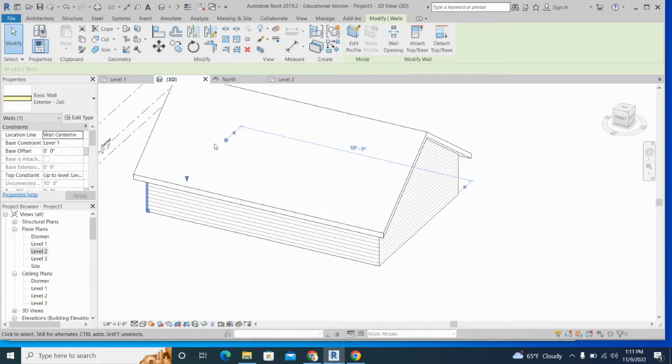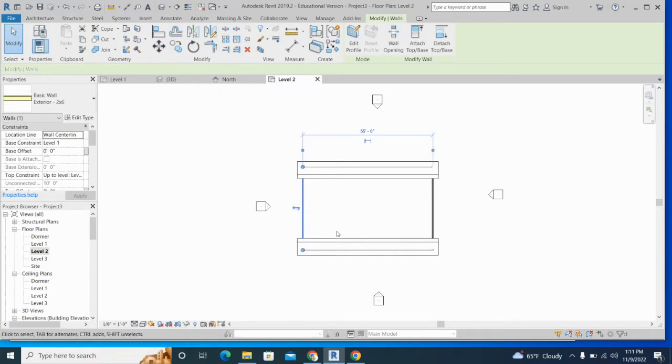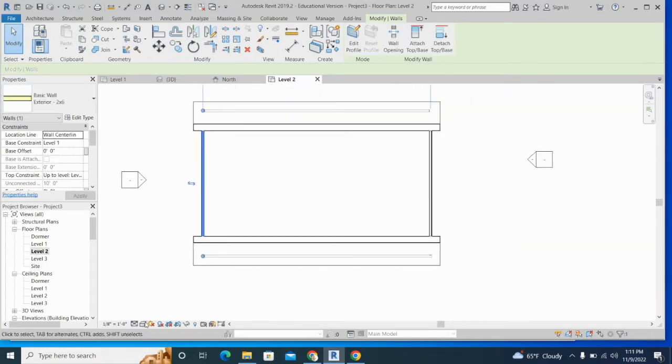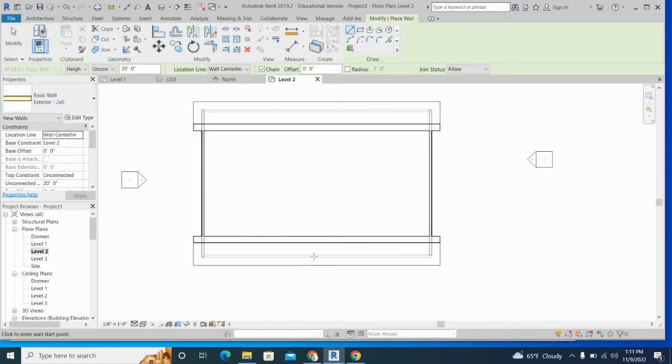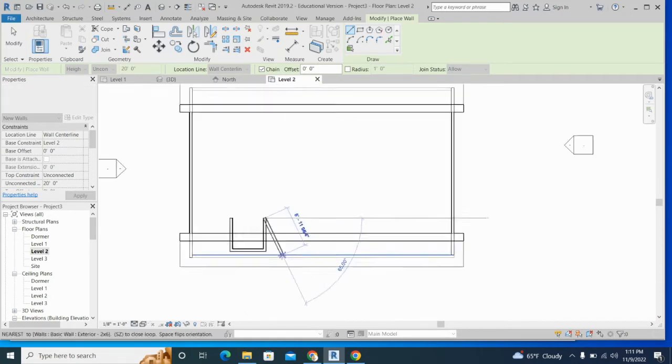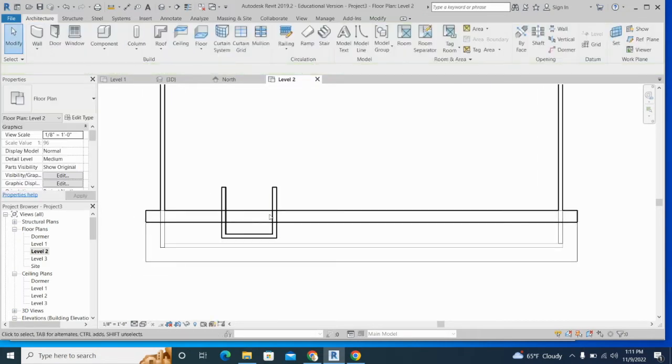All right, so our dormer is going to cut into right about here. Typically, you'd have an equal number or keep it symmetrical. Especially on a roof this long, you'd probably have 2 or 3. So we are going to go to our level 2 right now. And we're going to change to wireframe mode just so we can see all of those wall lines coming across. And we're going to go to wall, our exterior wall, and we are going to draw something like this. I'm going to make sure it's 7 feet wide. All right, so we'll start with that.